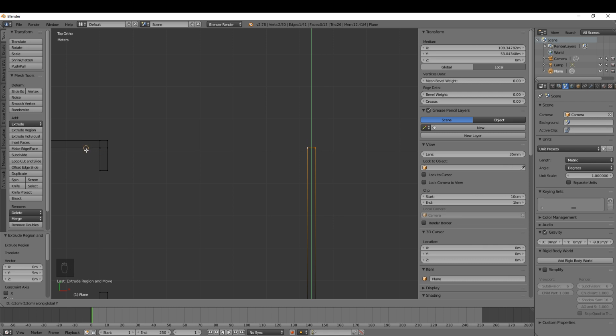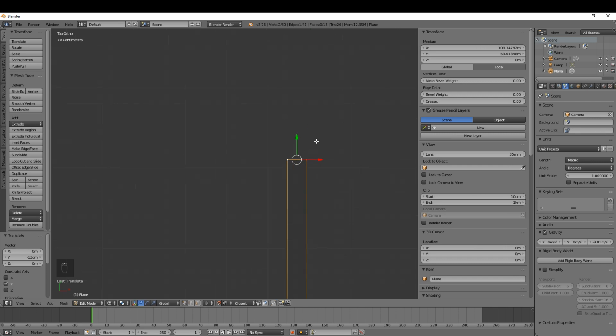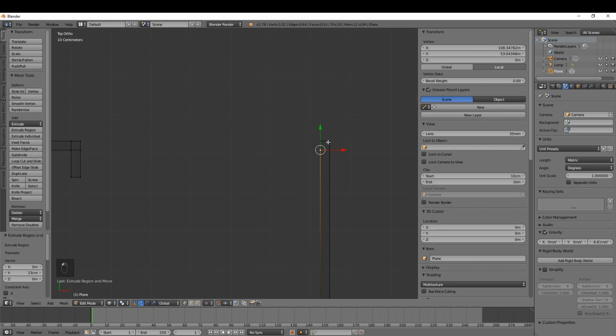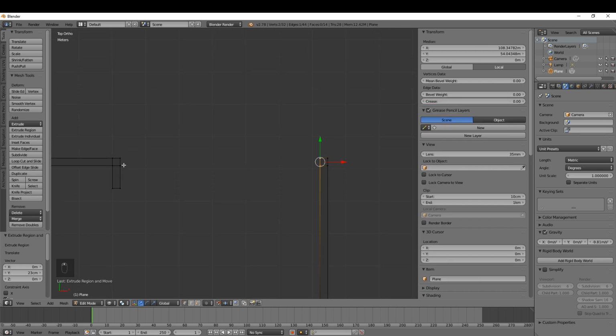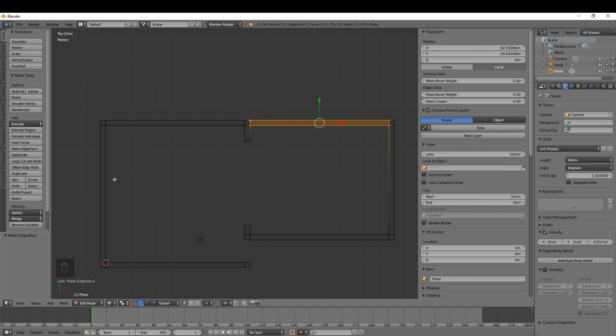In this case, you can see the little orange circle is snapping to this edge, so I'm just going to left click. Okay, zoom in. I can switch this back then to increment and press EY and come up 200 and 10, 20, 30. Okay, so simple as this. I can select these two, and just press F. Okay, and that's the exterior wall layout.